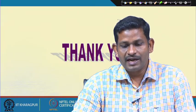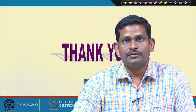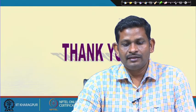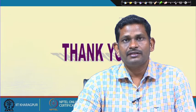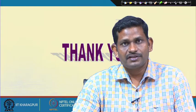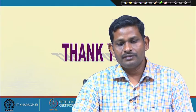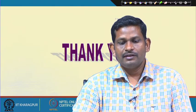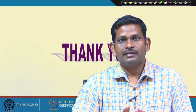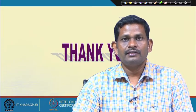in tubes, in pipes, we have differential pressure meters, like Venturi meter, nozzle meter, orifice meters, okay, and then again the trajectory meter, and then magnetic flow meters, okay, and deflection flow meters. And then finally the siphons. Okay. So, with these two lectures, lecture number 13 and 14, we cover most of the measuring devices for both open channel and pipe flows.